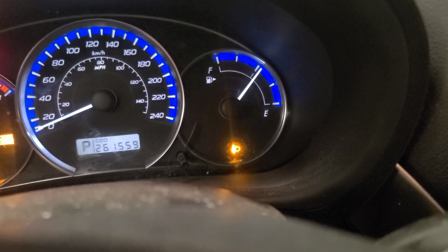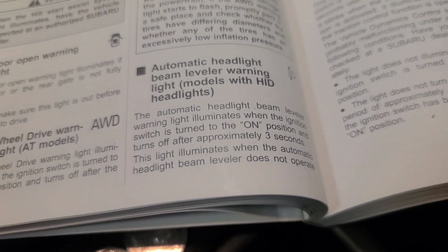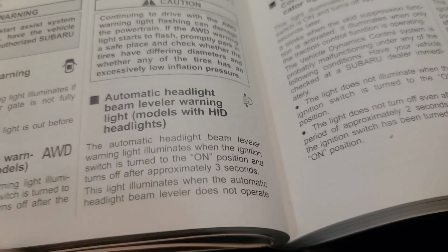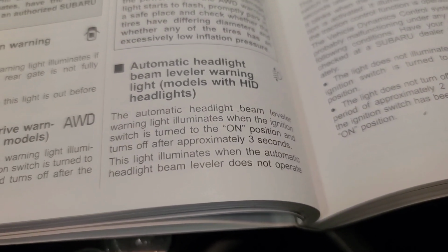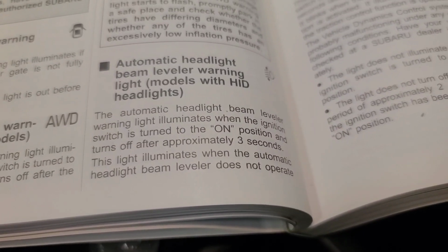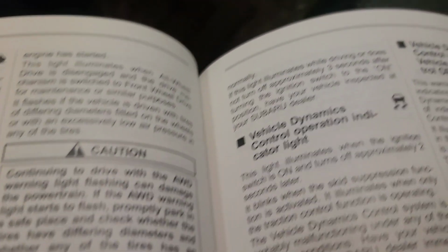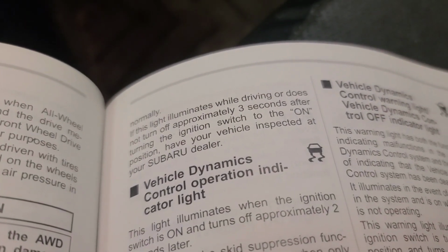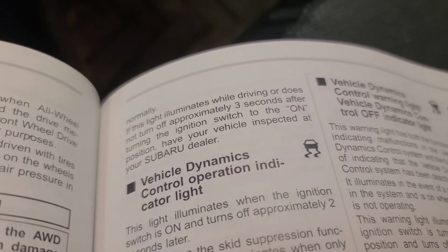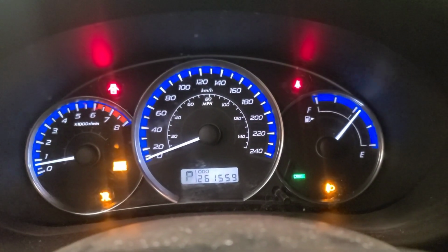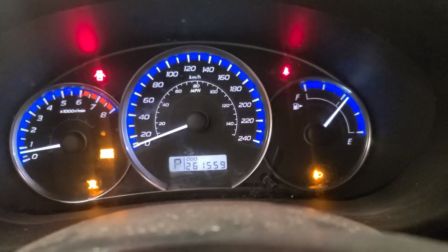So just following up, that indicator light on the bottom right is for the automatic headlamp leveling system on models with HID lights, which has it for the low beam. It was the high beam bulb that was burnt out, a 9005. I put one in. I assumed that was a headlight out warning message, but nevertheless there's a problem with the headlight leveling system. It says I'm going to take it to the Subaru dealer. There's no codes being generated in any of the controllers that I have access to with the Snap-on scan tool, so that's a minor issue. Just curious, that's all. Thanks.